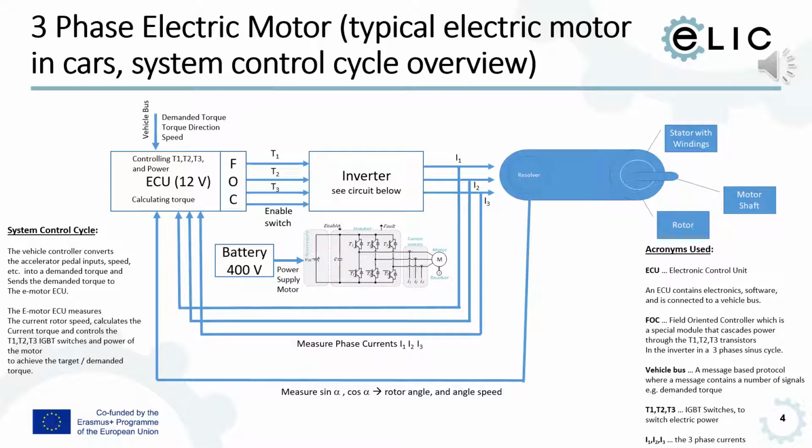Usually the field-oriented controller is based on a sinus shift of 120 degrees, a mathematical function used in trigonometry, because we place these different magnetic fields or coils in a circle with a 120 degree difference. 3 times 120 degrees is 360 degrees, which makes the full circle.